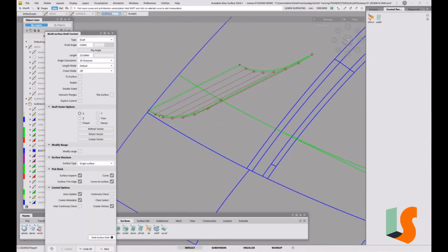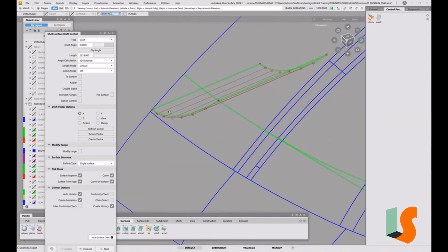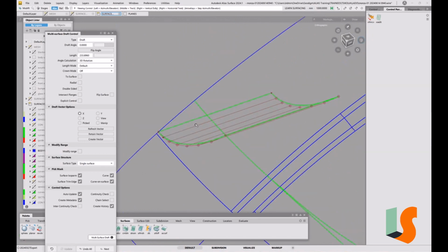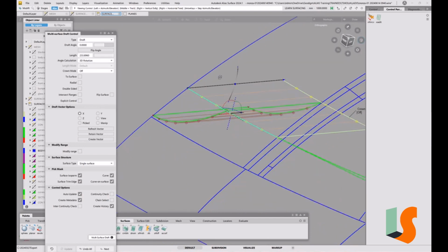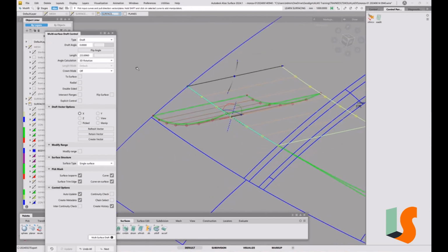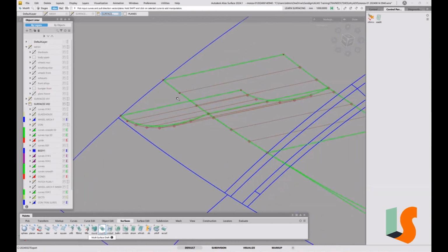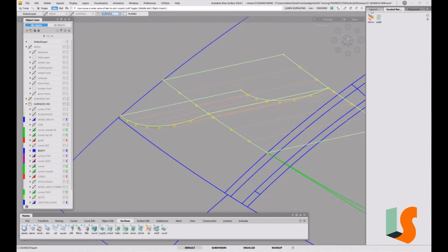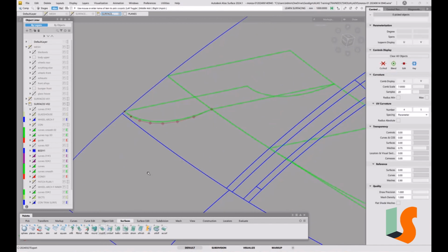This one shouldn't be such a problem at all because it's quite an open angle there. There should be no problem with the fillets there. But this one will be interesting to see what that does. And this one also I'll do in X for the time being because that's what it says on the mesh, but with history on. We'll take those CVs off. We don't need to look at those particularly. And then we can put in some fillets.